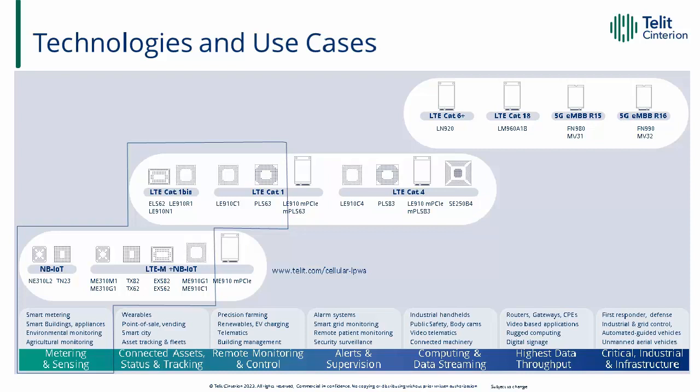Moving across to the right slightly, you see CAT-M has lots of variants, and I won't take time going through each one, but you'll find CAT-M only devices or CAT-M devices that support narrowband IoT. And some of these devices support LTE 450, which does need a dedicated 26 dBm transmission power, whilst normally the standard is 23 dBm. Sometimes fallback to 2G is required, so we have variants where you need this support, although truth be told, it's becoming less and less as time goes on.